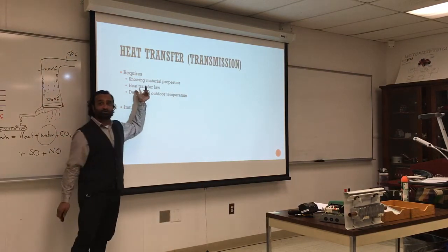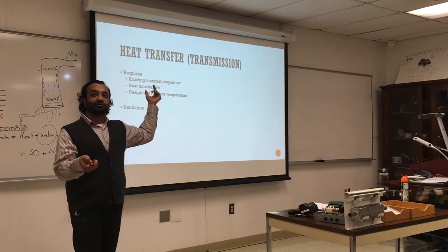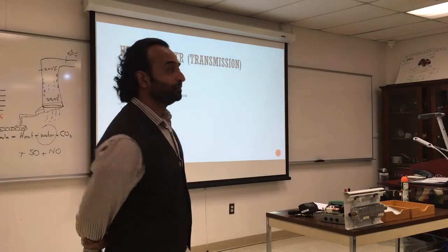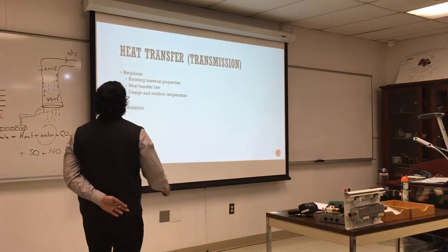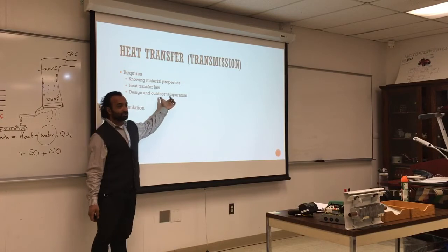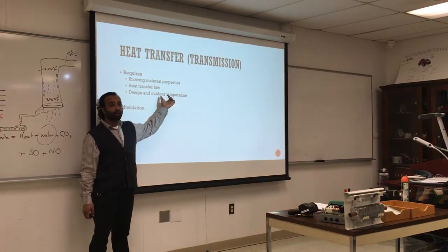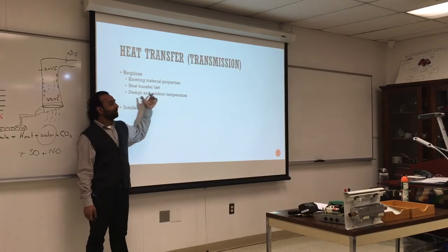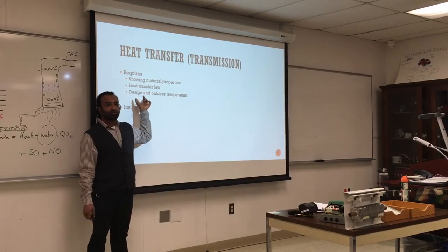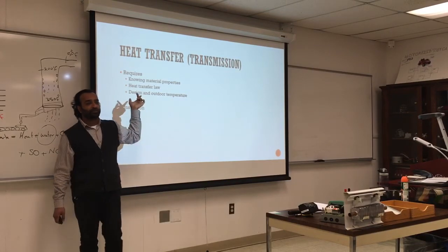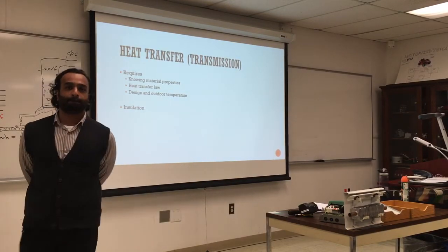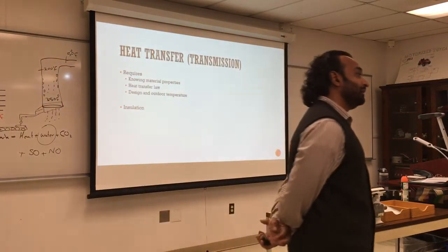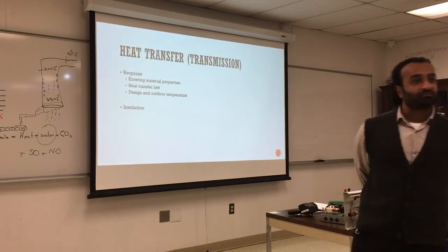You need to know the heat transfer law. What is that? It's over there on the board: Q equals A times U times delta T. And the design outdoor temperature. For heat, we design for the coldest day of the year, and that data is readily available online. And the design indoor temperature: how hot do you want it inside? That's something between 65 and 80. 65 is the standard, the lowest you can go, and 80. So that's the design temperature.